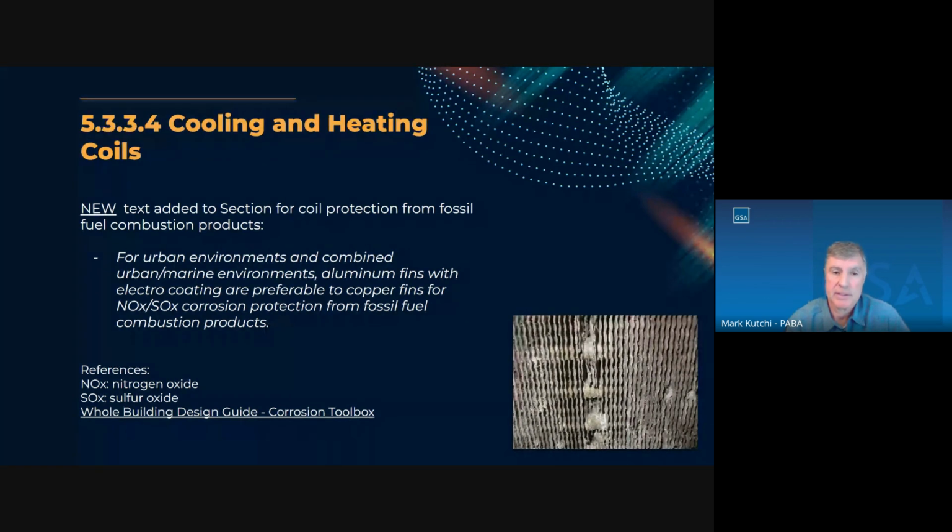Thanks for joining us. So in the cooling and heating coil section, new text was added for coil protection from fossil fuel combustion products. What was added is that for urban environments and combined urban marine environments, aluminum fins with electro coatings are preferable to just copper fins. This is to take care of the nitrogen oxide and sulfur oxide that are present from